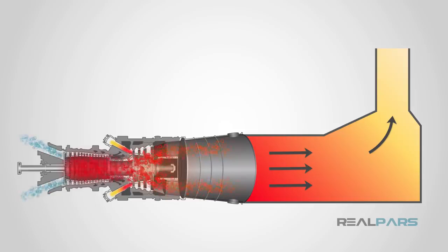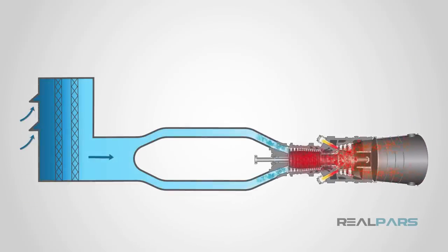With this quick review of key components of a gas turbine, I think it's time to decrease the altitude and elaborate on the system further. As I mentioned earlier, air is let into the gas turbine through an air intake. The air is prone to contamination or having some unwanted particles which can harm the system and degrade the overall performance.